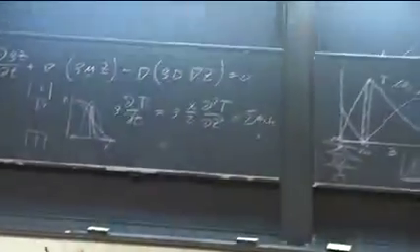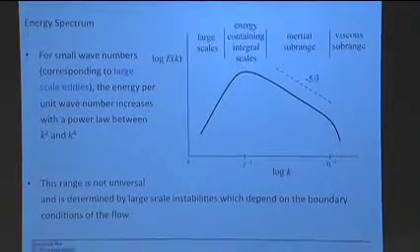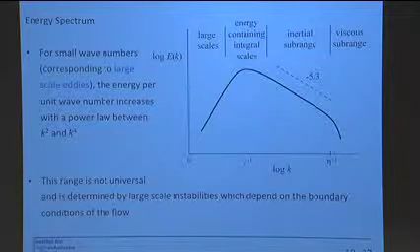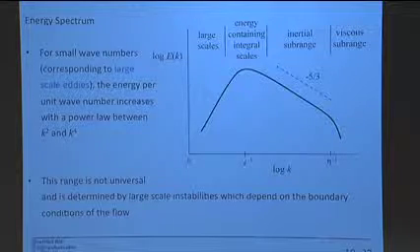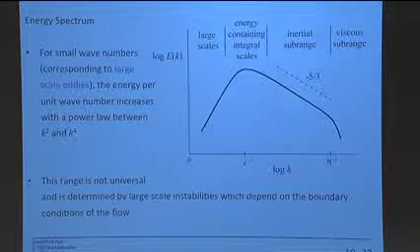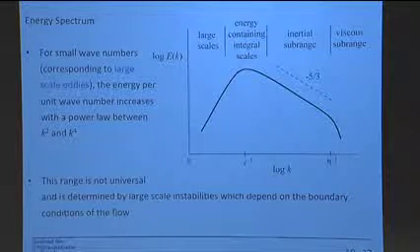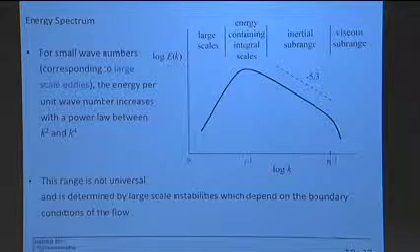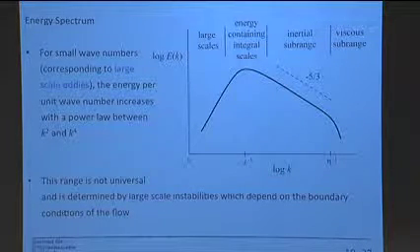This is a logarithmic plot, and what it shows is that there are certain length scales where the turbulent kinetic energy is very large. If you go to smaller length scales, which means larger wave number, the turbulent kinetic energy gets smaller and smaller. Since this is a logarithmic plot, this is a lot of energy, and if I go here, then there's no more energy. So the energy in these eddies essentially can be neglected for the total energy.